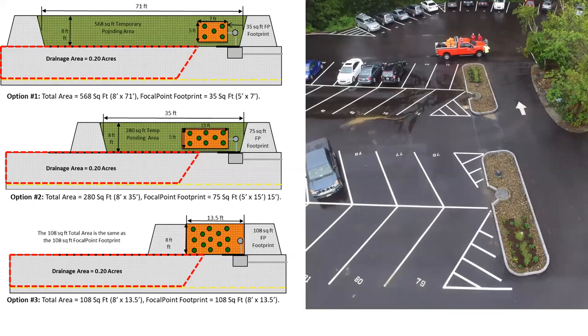And then if you get to the point where you really don't have a lot of room for surface storage, then at those times, a lot of times your whole vegetation footprint needs to be that engineered soil or filtration bed. And so this is really advantageous for designers because what they can do is leverage the size of their bioretention system based off of how much surface storage they have. And so that can make it a little easier to design these systems.